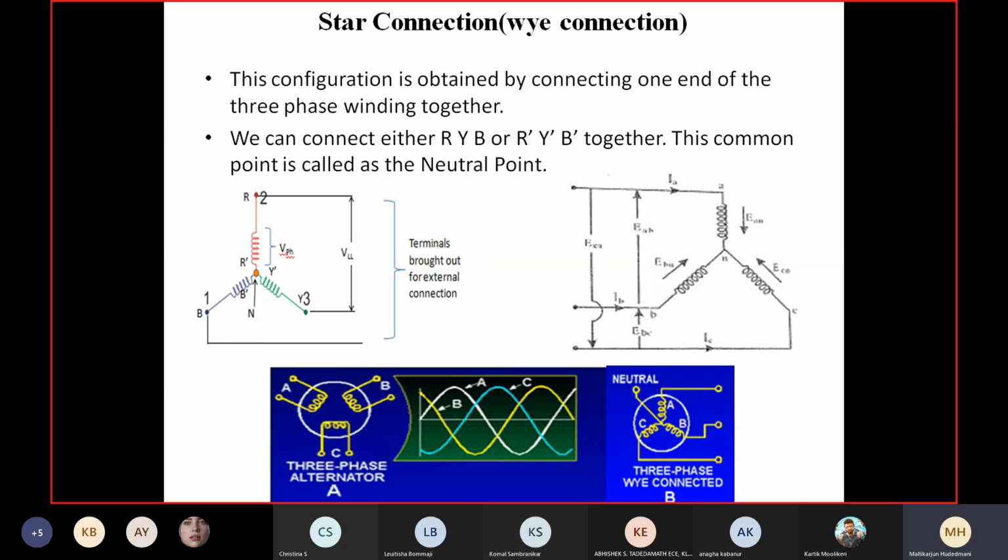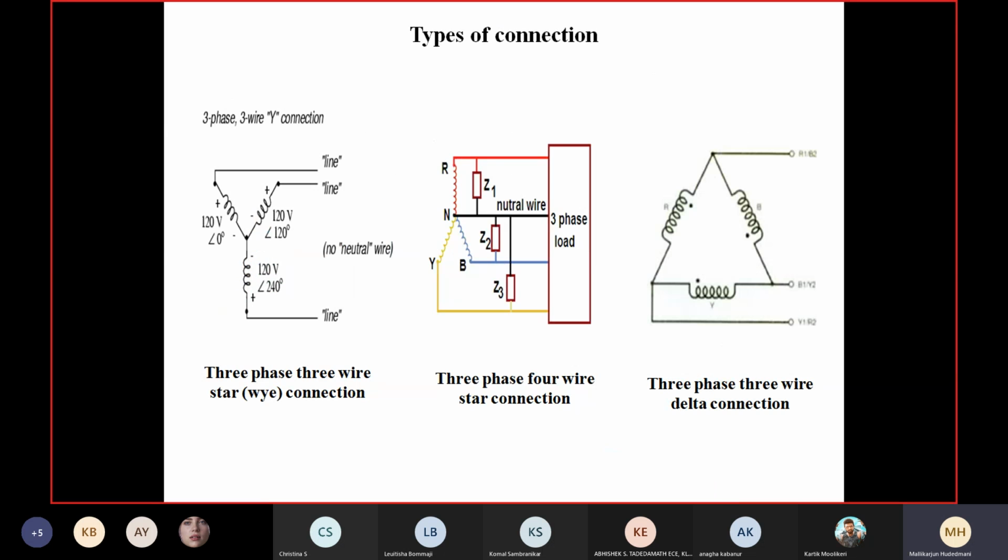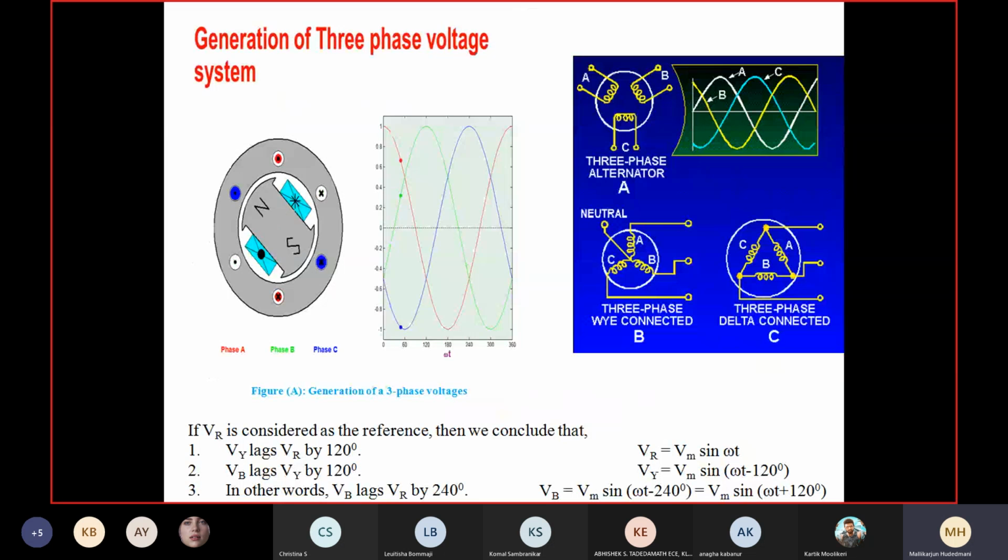In the three-phase AC circuit subject, in the previous class, we saw how the generation of three-phase AC takes place, and how the rotating field mechanism induces an EMF in all three windings symmetrically, in balanced mode, as Vm sin omega t, Vm sin omega t minus 120, and Vm sin omega t minus 240. The running cursors on the wave show how the individual phase waves are drawn, and another view in the top right corner shows how the three-phase waves are drawn on the scale.